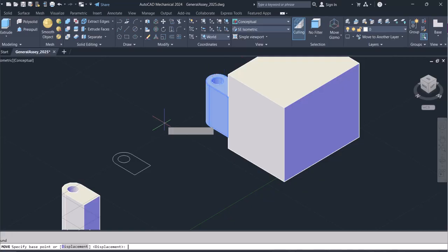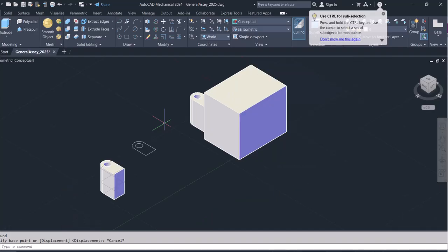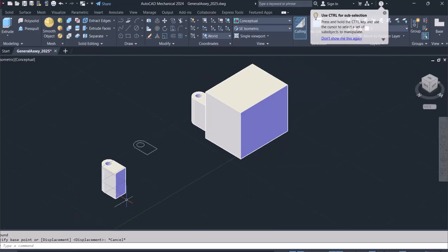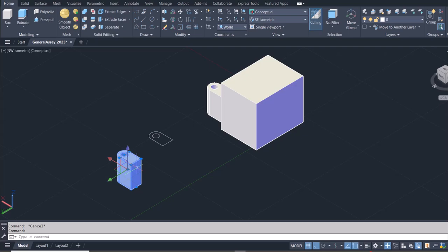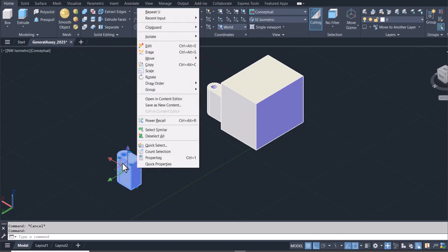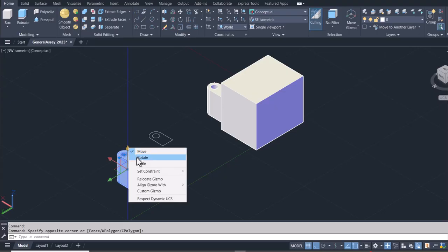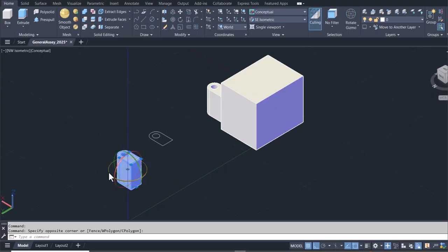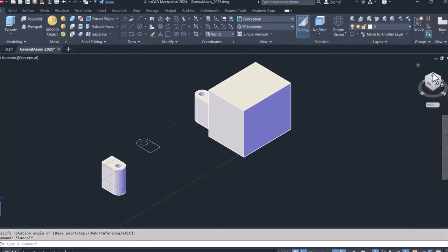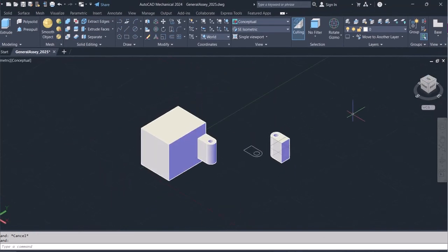Okay, and then enter. That's good. So now we'll click on this, right click on the axis, close to the axis, and you select rotate, and we want to rotate by the Z axis by 180 degrees. So I turn that this way, I click, then hit escape. Now let me turn this around that way.